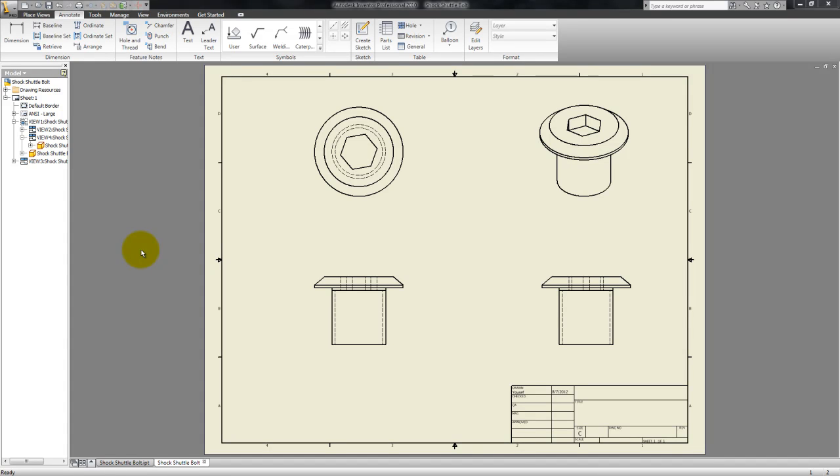So finally we'll get on to the important dimension box in the Annotate tab. Just like dimensioning sketches, we've got the general dimension. If we just hit D or click that, we can pull off diameters, just lengths, piece of cake really. Something you should already be used to, dimensioning sketches. So that's how you do all that. And remember, make sure I don't duplicate dimensions. But some other tools exist that we can use.